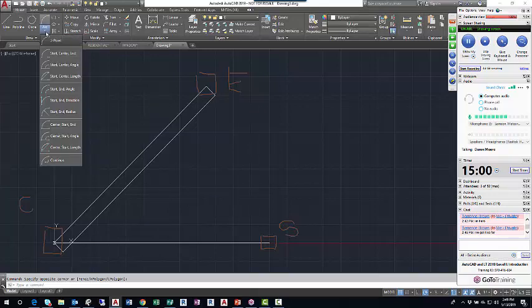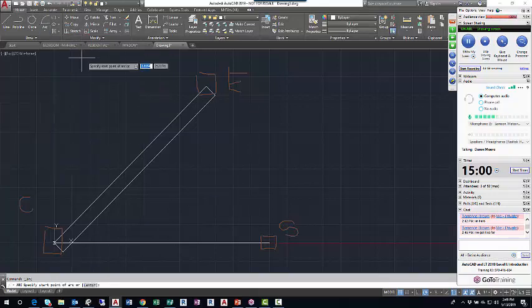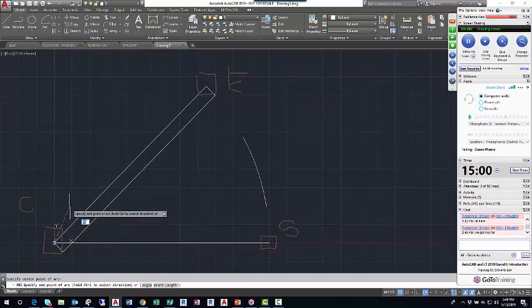So I'll open up where the arc tool is. I'll click Start, Center, End, and I'm going to follow the prompts. The first prompt says Specify Start Point of Arc. So I'll left-click the left end point of that arc. Then the prompt says Specify Center Point of Arc. Let me back that up. I'm left-clicking the right end point of that horizontal line. I may have said left. I click the right end point of the horizontal line. Now I'll come get the left end point of that same horizontal line. That's my center. Left click. Then finally I go to the high point of that rotated rectangle, and I'm going to left click. That's the end point of arc. I'll left click, and that ends the command.